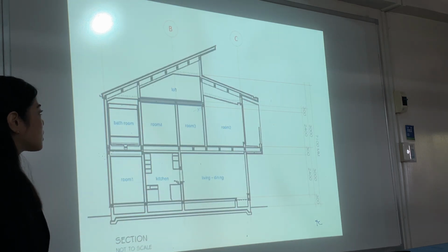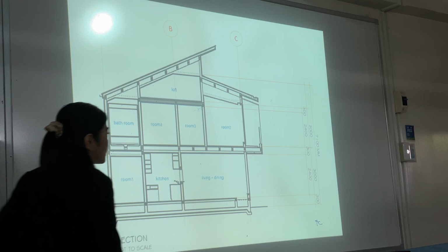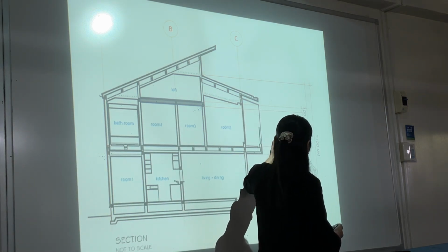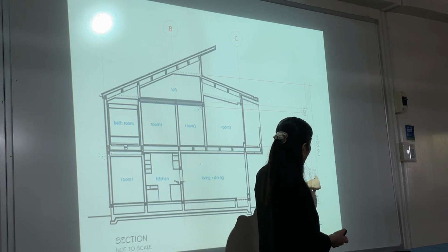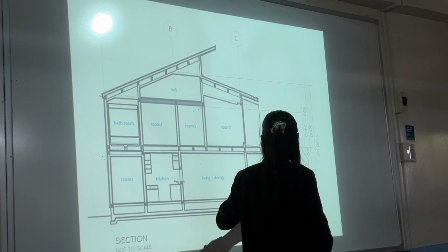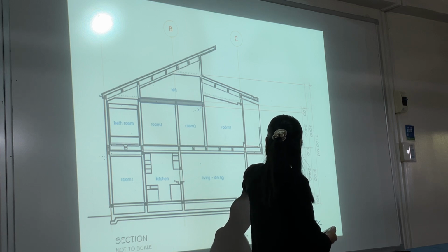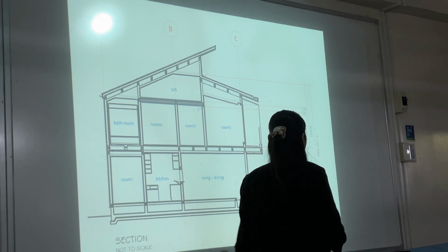So again, in your section later, you can use this one. This is the proper way of dimensioning. First, break down the small pieces of information, and then from there, total them. Why is this totaled at 3 meters? Because this is your ground floor total height: from your ground floor to the ceiling height, and then the slab thickness, which is one detail. And then, finally, the total.